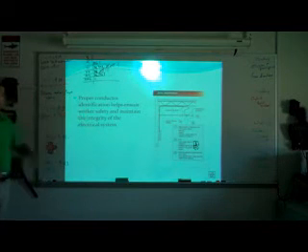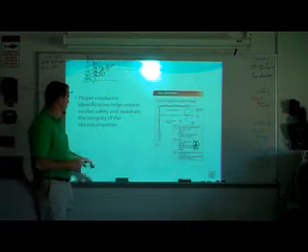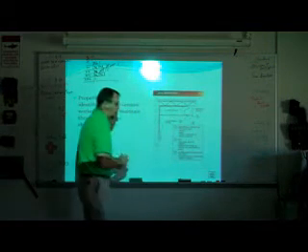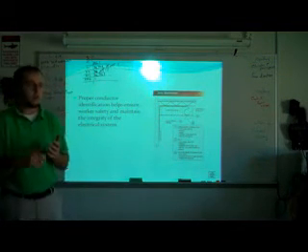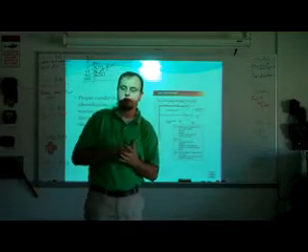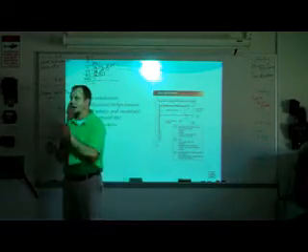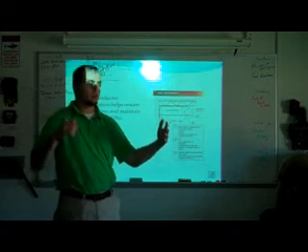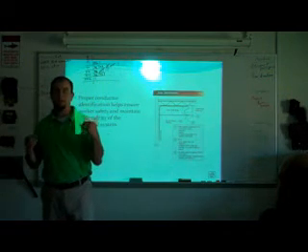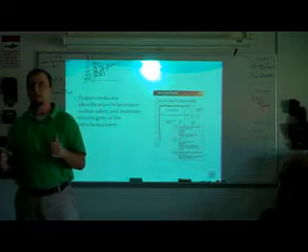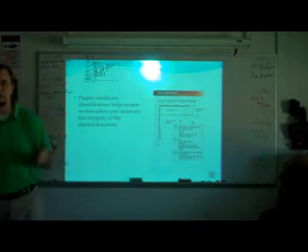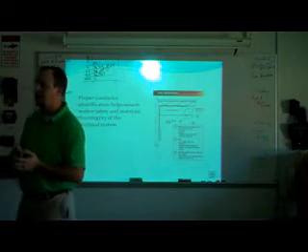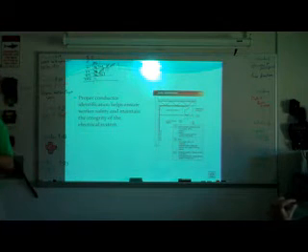Proper conductor identification helps ensure worker safety and maintain integrity of the electrical system. Okay, let's start to talk about colors. There's a reason why the color system is set up. It's so that I install it, and Pat can go back and troubleshoot it because he knows that I use red as my power wire, white is my neutral, and green is my ground. He doesn't have to go back and double check everything that I've done. He knows that this is an ungrounded conductor, this is a grounded conductor, and that one is a ground. That's why we use a color system: for easy identification, for safety, and for faster troubleshooting.